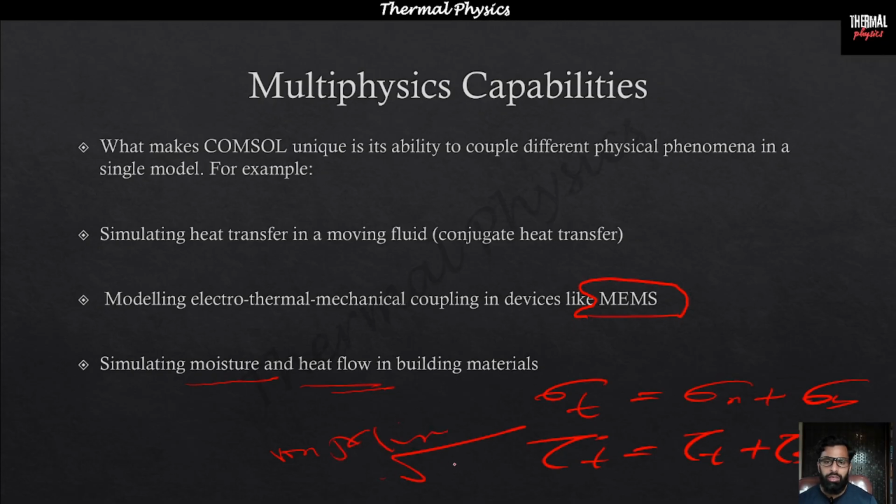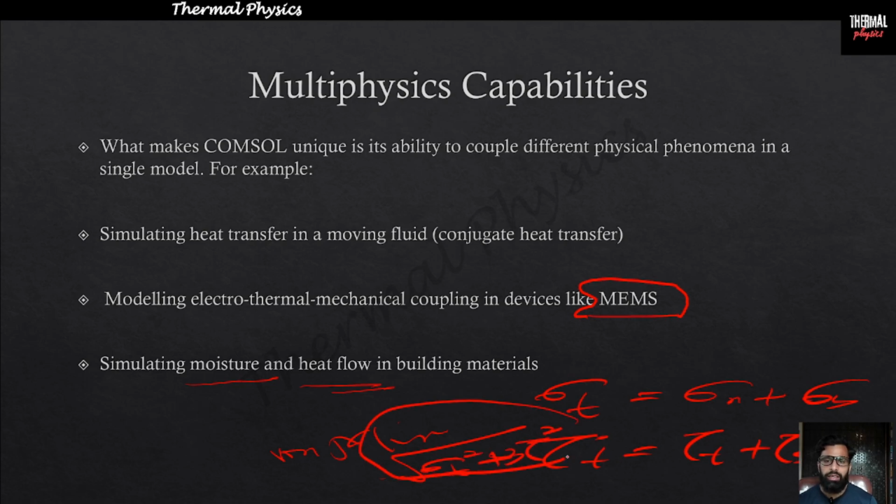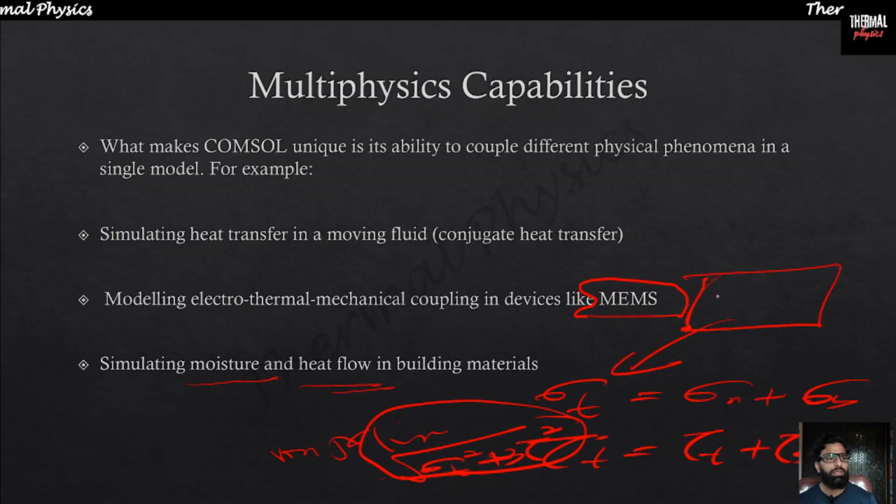For that we will do sigma square plus 3 times tau square, and this we will use for the failure criteria. This will tell us the critical stress in the prismatic bar and what material or what thickness we should choose for it, so that it will keep functioning where it is used without failure.